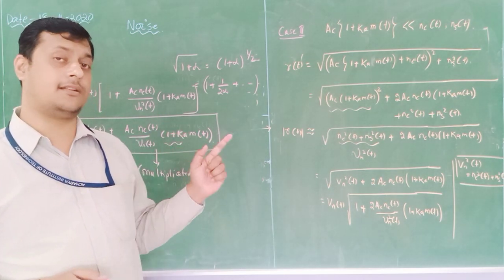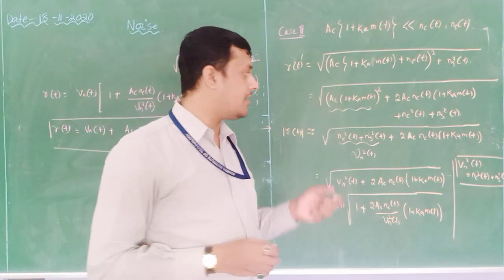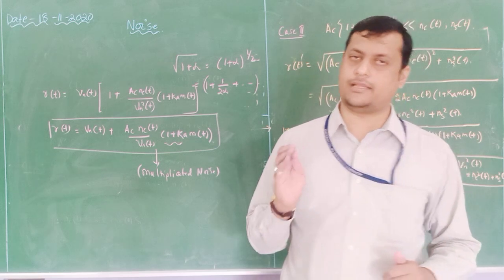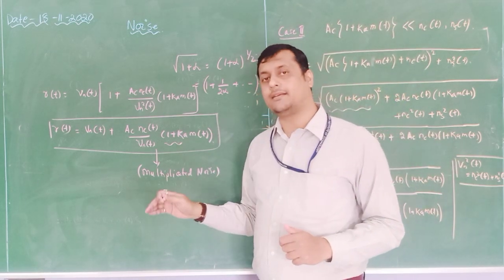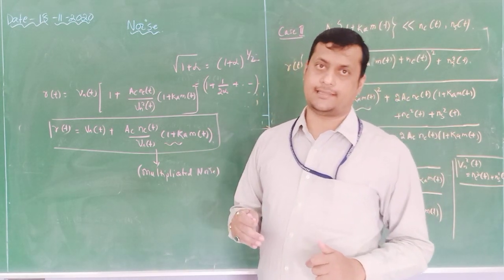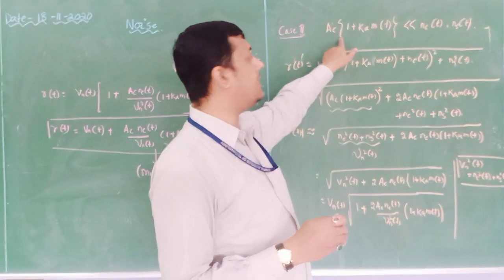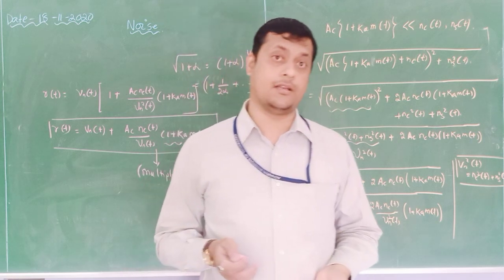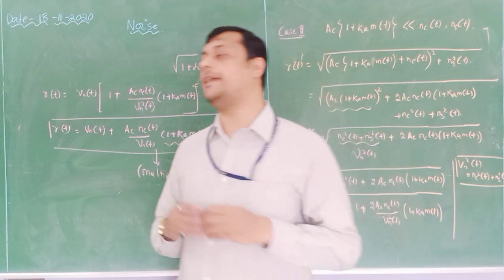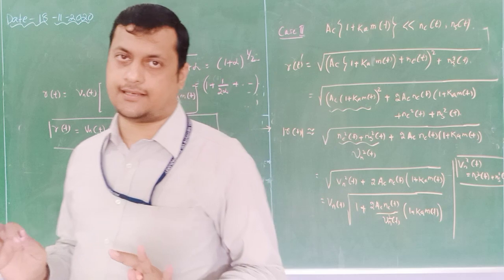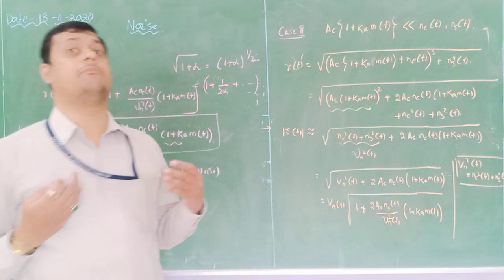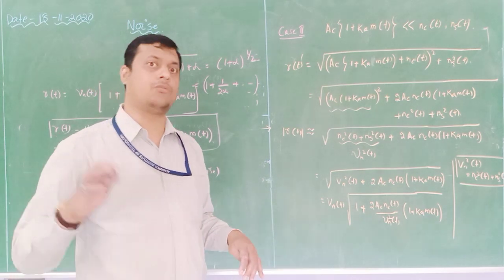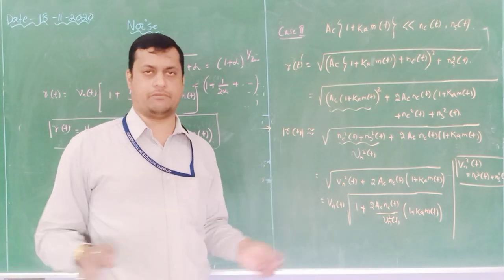We have seen synchronous detection, and now we have discussed envelope detection. Always remember this: in envelope detection, in the second case, if the modulated signal amplitude is less than noise, we get multiplicative noise. Multiplicative noise makes it very difficult to extract the modulating signal. We cannot minimize the effect of noise. The effect of noise is so high that the original signal cannot be recovered.